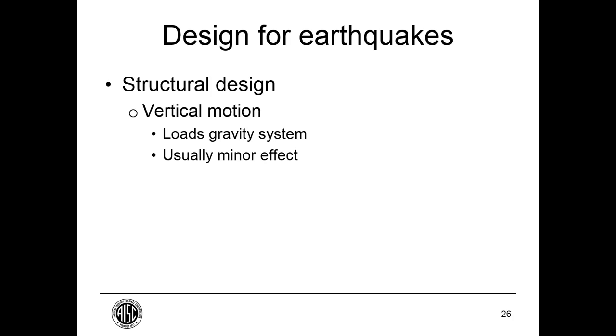There are many structures that are highly sensitive to vertical accelerations: large cantilevers, long spans, and the like. And those may need to have a little bit more attention to quantify what the vertical acceleration is and to see what the response is. But for typical structures, the vertical motion is not something we focus on very much.